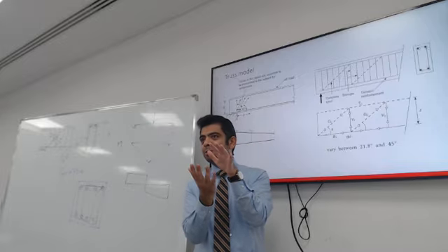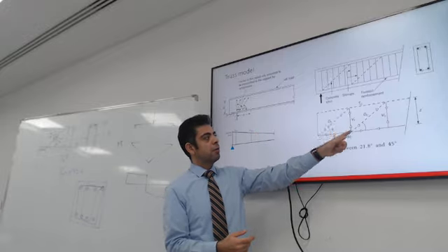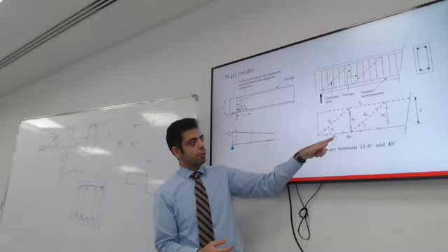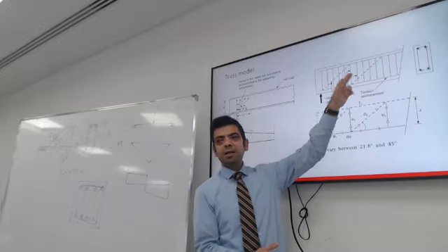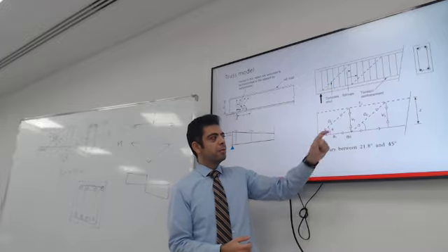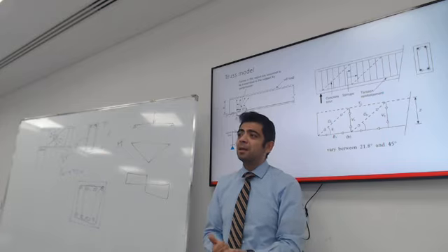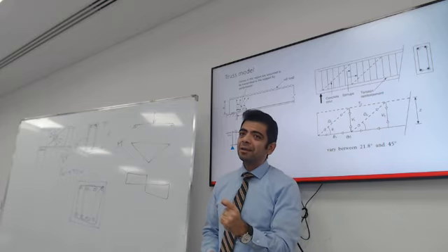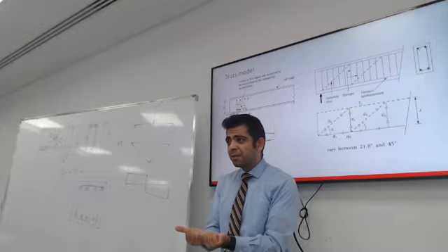The shear forces will result in mainly three forces: vertical force, horizontal force, and a diagonal force. The vertical force is tension in the stirrups. The horizontal force is tension in the longitudinal bars. So shear will add additional tension in the bottom reinforcement.